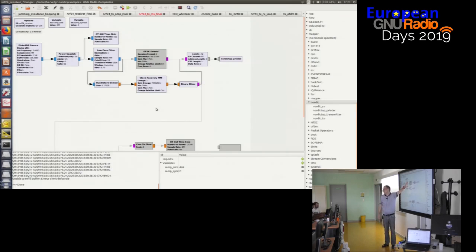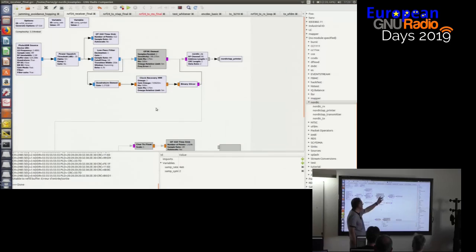You can take the block from the library if you don't want to see what this GFSK demod block does, but it's interesting to see what it does because in fact it uses these 3 blocks, and that's interesting to understand how GFSK demodulation works on a digital system. And the code is quite well documented and it's quite nice. For example, it gives you the explanation about the gain you've got to put in here according to the number of samples per symbol you've got.